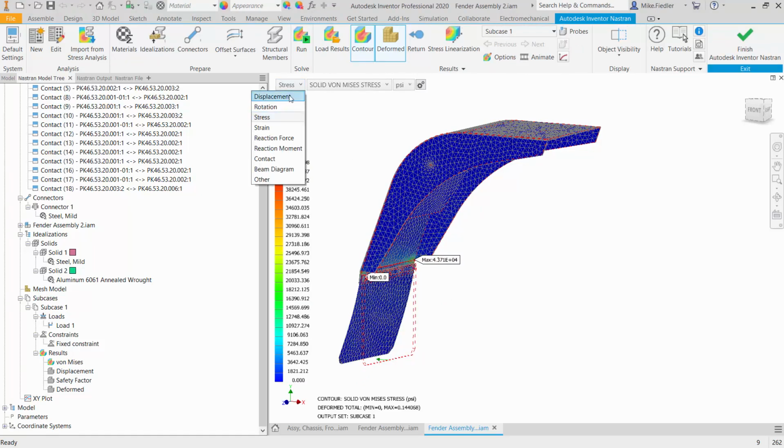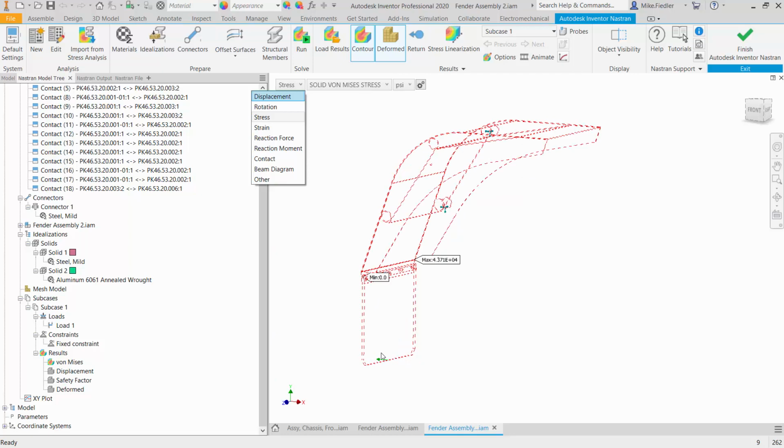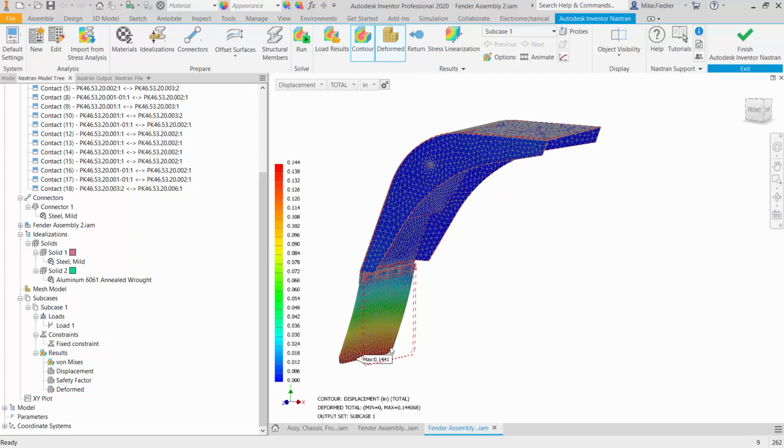And let's take a look at the displacements here. I'm going to expand upon that in just a moment. We put the load directly on the flap, right? And the results here hopefully show that our flap doesn't go flying off into space, which it doesn't. We can see the maximum displacement for this model is 0.144 inches, so a little more than a tenth of an inch, almost 2/10 of an inch, between 1 and 2/10. But you know, happy to see that it all remained connected there, right?